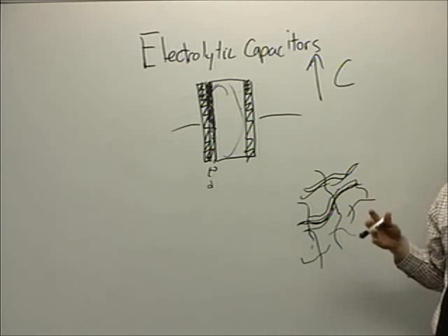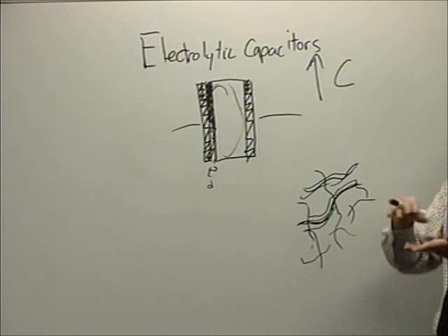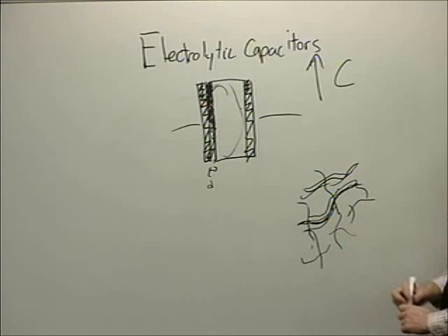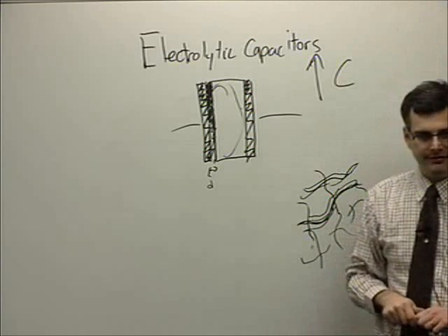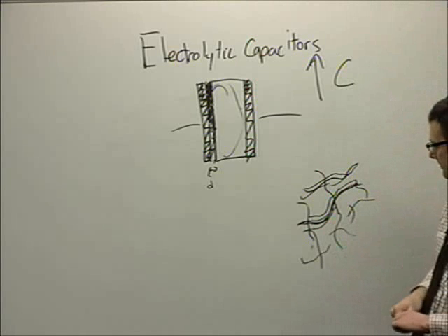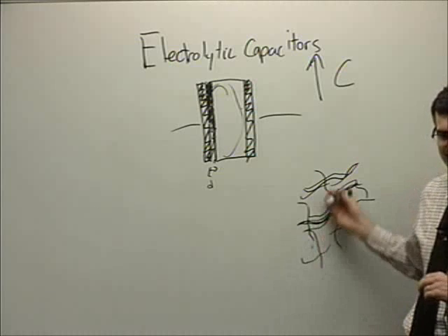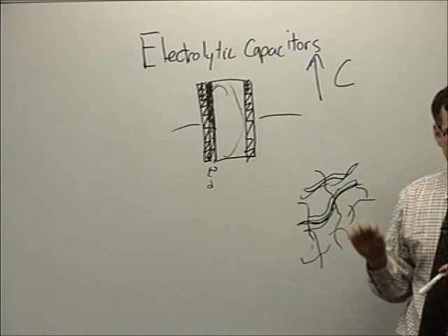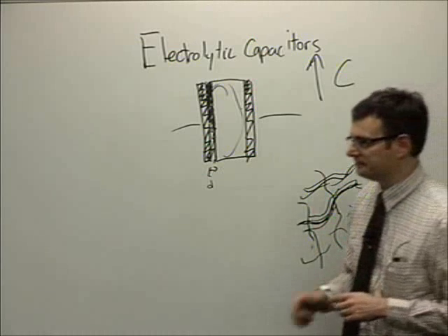So it winds up being many, many orders of magnitude larger than a little plate that you put in a comparable cross-sectional space. And so your capacitance goes way up. So if you ever see the term supercapacitor, they're probably playing some trick like this with the innards to give it a super high value of capacitance in a very small area of space.